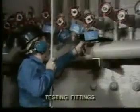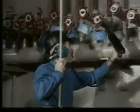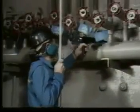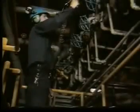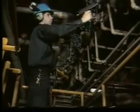To test fittings such as valves, piping, and flanges, scan for a rushing sound or white noise. Use the scanning mode of the ultraprobe as shown earlier. Adjust the sensitivity to move from gross to fine sounds, and move back and forth to confirm the leak site.